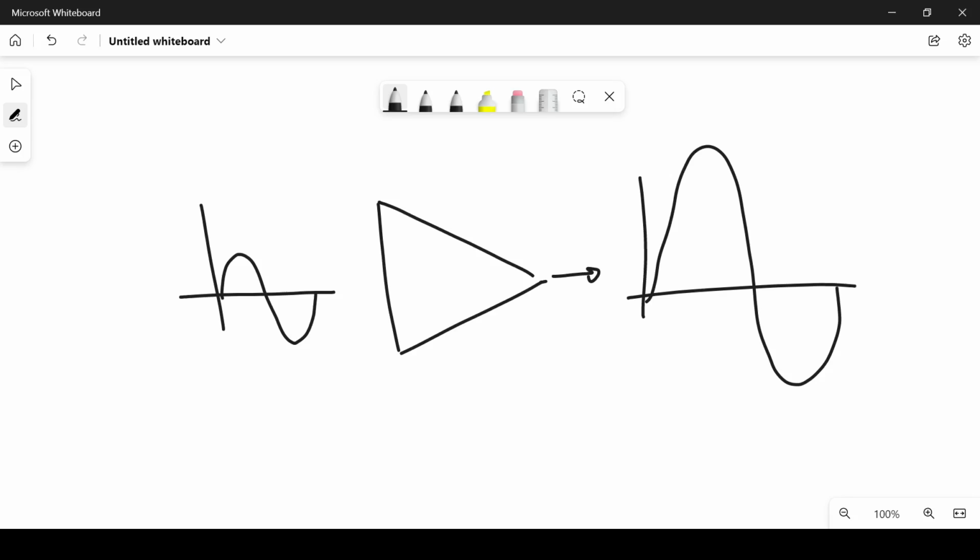But we have said that this operational amplifier takes 5 volts from the power supply. So the maximum value that the signal could take is 5 volts. So if we give gain to this signal and the maximum is going to be, for example, 6 volts, that is not going to happen.